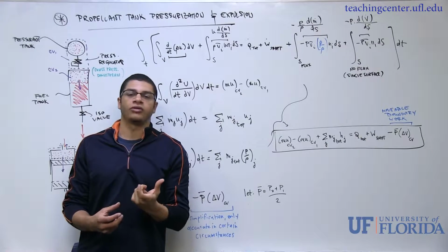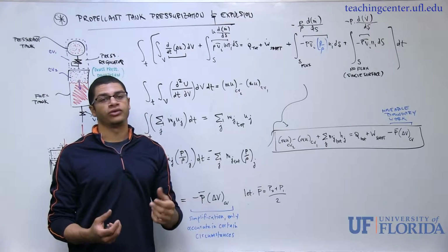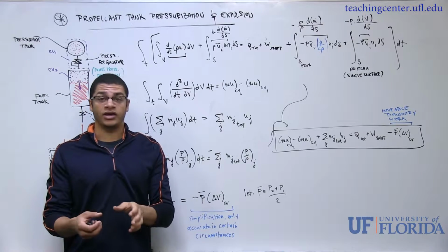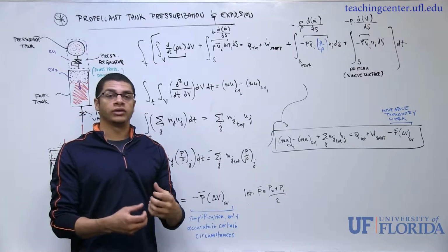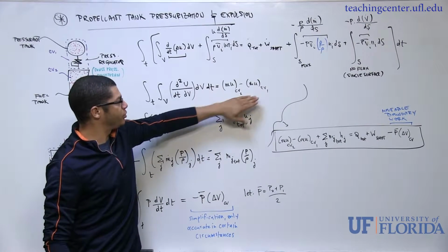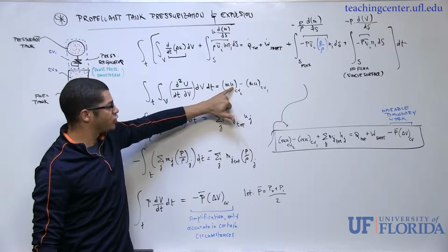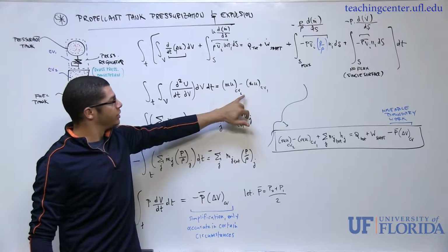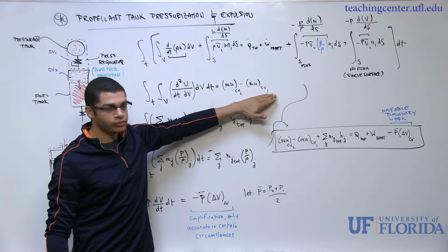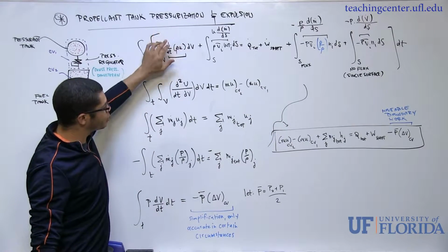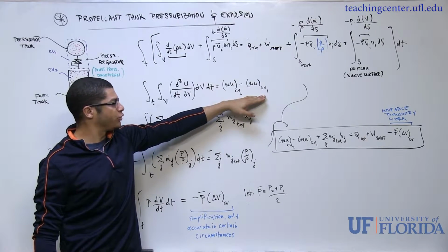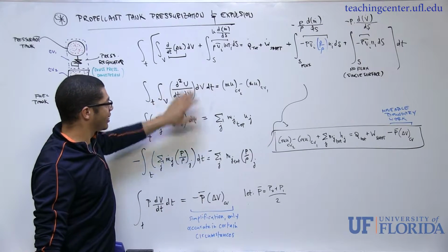And then capital U itself, the total internal energy, can be broken apart into little m times little u, or the mass times the specific internal energy. And so dmu can be integrated, and you arrive at simply the mass times the specific internal energy of the control volume at state 2, minus the mass times the specific internal energy of the control volume at state 1. Okay, so this ugly looking expression has simplified down into two nice things that we can calculate pretty readily once we get down to it, after I've integrated with respect to time.